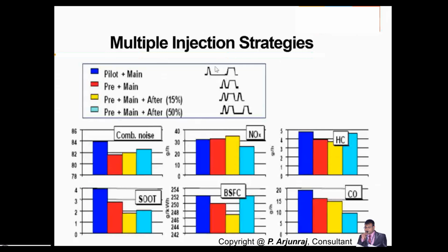When I'm giving this delay period, the peak temperature is going to be reduced, which means you have a delay period of mismatch, so you are not going to inject in time. In that case, you don't have the combustion at that point of time, which means your temperature is going to be reduced. It means there is a possibility that your nitrogen oxide can be lesser, but at the same time your particulate matter will be higher because of this. The particulate matter is also called soot. The soot is going to be higher because of this, and you get lesser NOx, however.